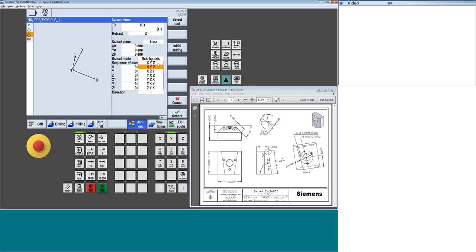If you want to get in the habit of always telling it the axis you're rotating as the first, that's okay too. So here we're going to do a 9-degree, and it's a -9. How do I know that? The best thing you can do when you're getting into programming in 5-axis is get yourself a coordinate cube. The coordinate cube looks like that little image I was showing you, but it's a physical cube you can have in your hand, and you can tip it around in space and start to see the direction that you would need to go to get the tool normal to that angle.